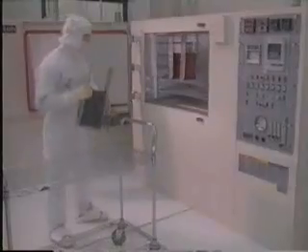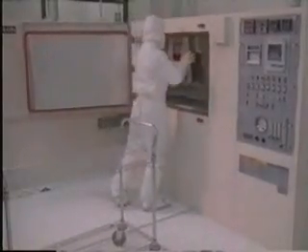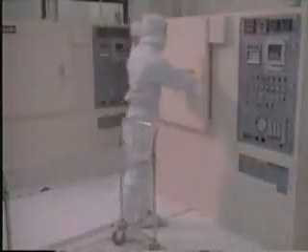Adhesive is placed in the cavities of a strip containing 4 lead frames. Each die is properly positioned and placed on the adhesive. A gentle scrubbing motion ensures a good contact. In an oven, the strips are exposed to high temperatures to cure or harden the adhesive.